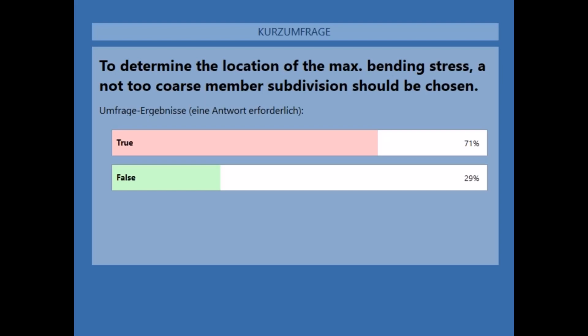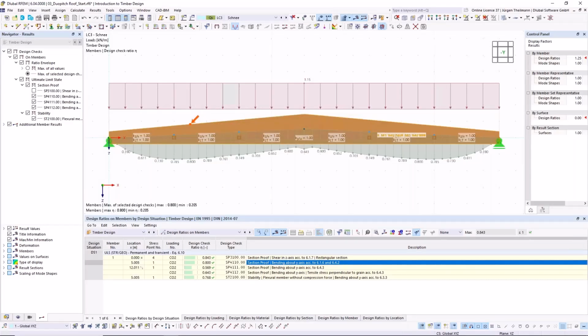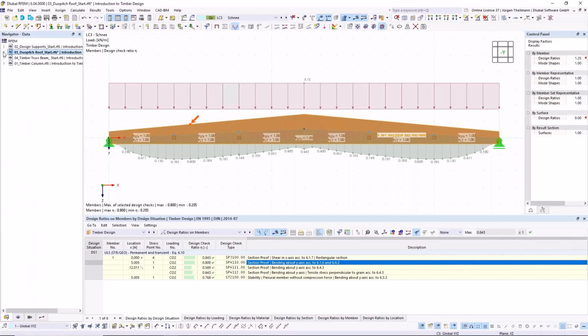So this one I have now is too fine. The first one I showed you with the 24 subdivisions would be accurate for this example. But don't forget, this is a job of you as upcoming structural engineers to always have in mind that you need to check the size of your mesh. Good. Now for the fourth and last example of today.